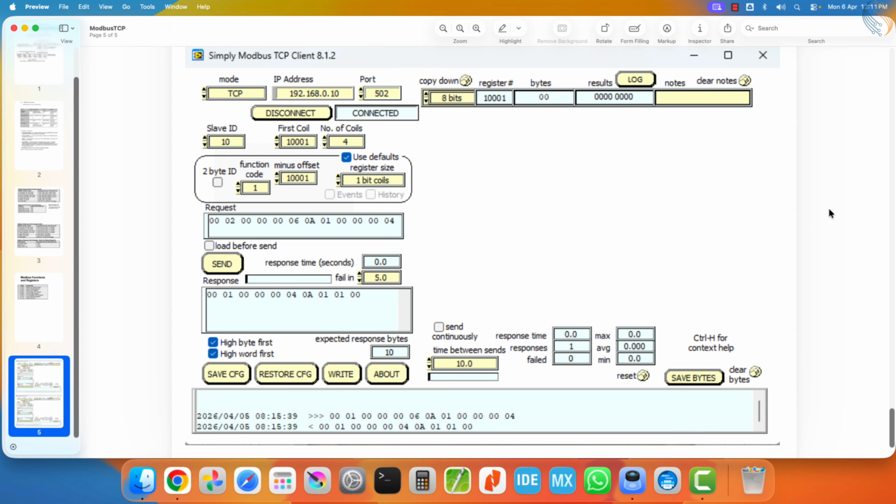For example, if the server receives a request for coil data, we just need to write functions that provide the coil data to the response. The rest of the frame construction, including the MBAP header, function codes, and all the protocol details, will be handled automatically by the Mongoose library itself. We will see exactly how this works throughout this series.